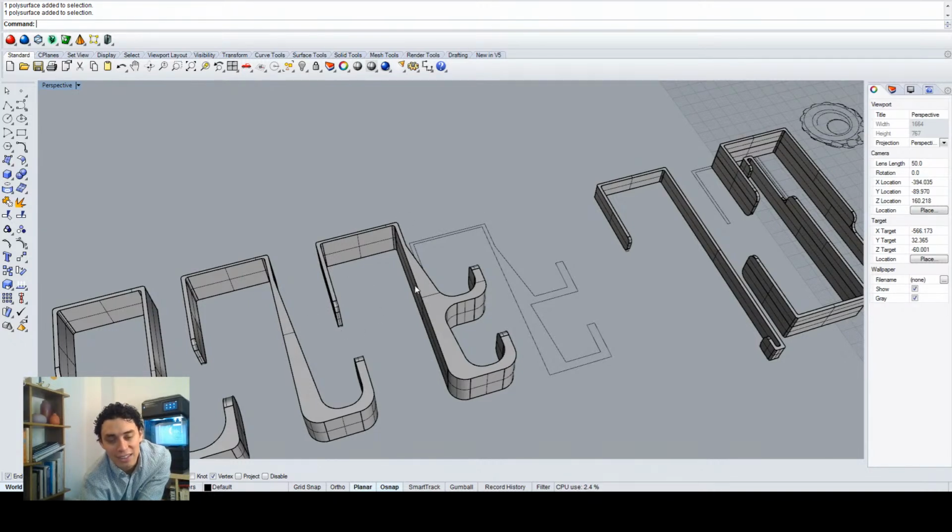instead of flowing flat through it, it's going to increase the amount of material that I have, the strongest materials that I have, because of the infill, unless I'm using 100%, which I definitely could, but I didn't really want to do that because for this part, it ends up being a little bit of a waste of time and material. But adding a little bit of detail here will add strength to my wall, surface area to my wall, and ultimately will create a beefier part.